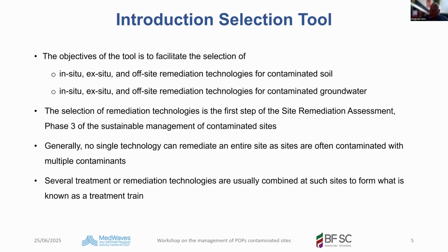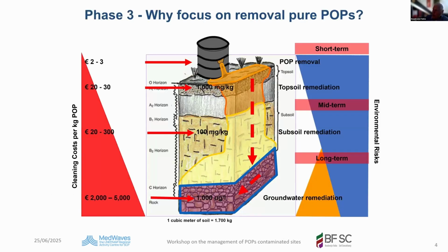As you should be aware of the product in the vessel. Let me go back to you know what product it is. It can be PCB oil. So PCB and oil should be then the components to be analyzed. So you install wells which are reaching the groundwater, and then you analyze for PCB and oil. And PCB is maybe expensive, so you may use oil as a tracer. And then later, when you have, let's say, mapped the plume, you can then take some representative soil samples to get the full scope of the contaminants of concern.